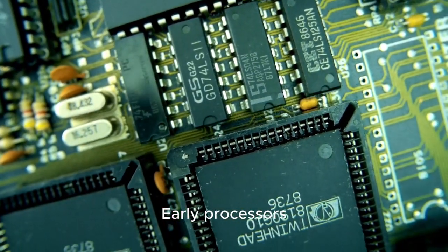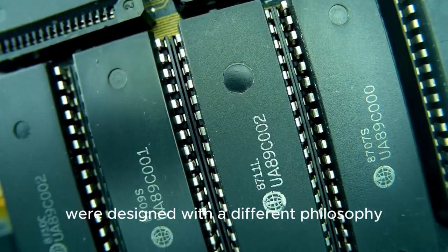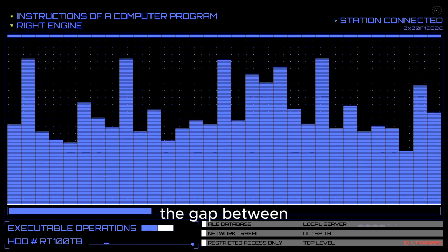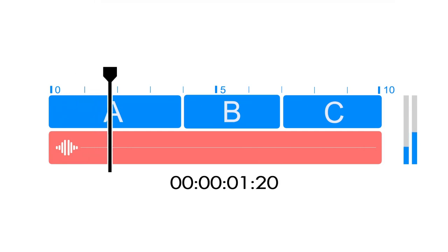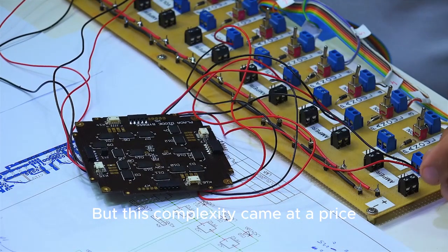Early processors, now often called CISC or complex instruction set computers, were designed with a different philosophy. The idea was to make the hardware as powerful as possible to bridge the gap between high-level programming languages and the machine code the processor actually understands. This led to processors with hundreds of complex instructions. Some instructions could perform multiple operations at once, like loading data from memory, doing a calculation, and storing the result, all in one go. But this complexity came at a price.